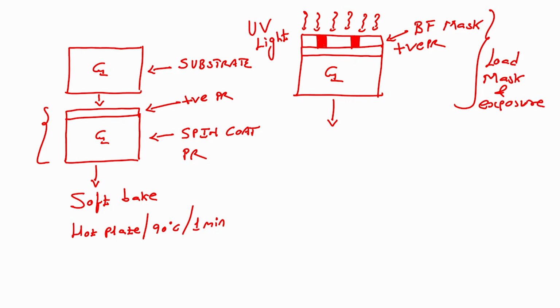After this particular step we will go for unloading the mask. After unloading the mask, the next step would be photoresist development. You have to develop the photoresist, so we will dip this wafer in a photoresist developer.